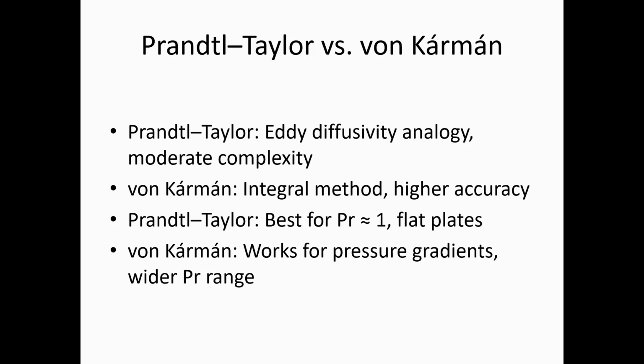The von Karman integral method gives higher accuracy. Prandtl-Taylor is best for a Prandtl number of approximately 1 for flat plates. Von Karman works for pressure gradients and a wide Prandtl number range.